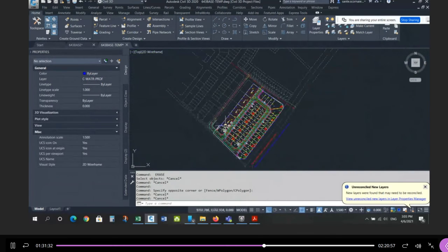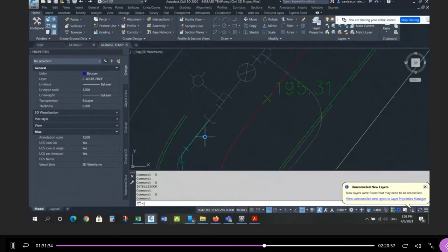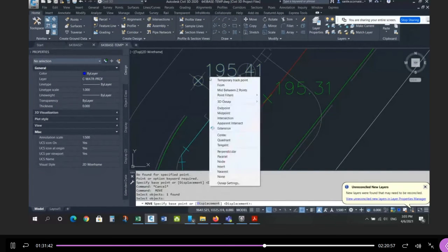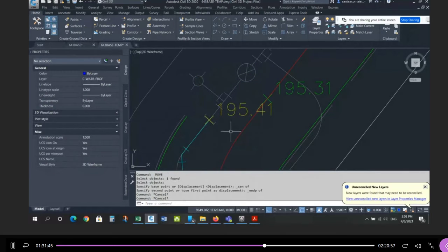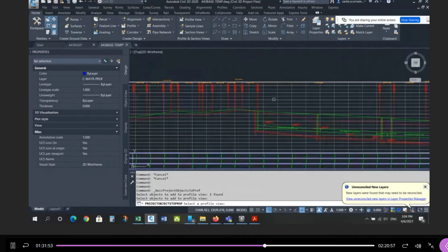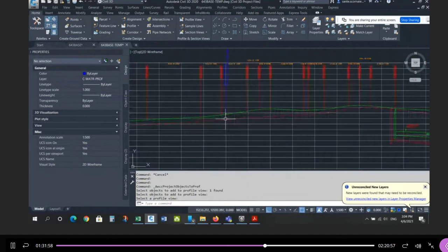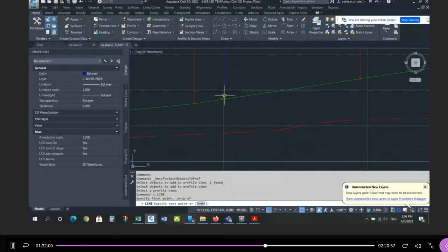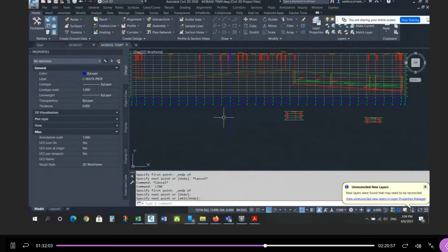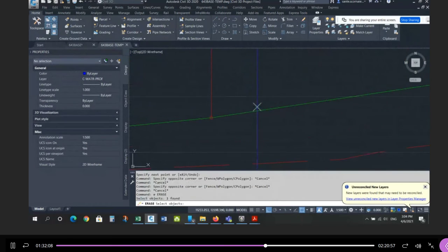So you're going to draw, let me just project that point, sorry. I'll go back. Move this point from center to end point. That's the beginning of the system. So we're going to project this point. And again, it's just the station you're interested in. You can use that elevation or not, it's up to you. So there's where your design starts, right there. Everything on this side is existing, everything on this side is proposed. And that's where your plug will be.